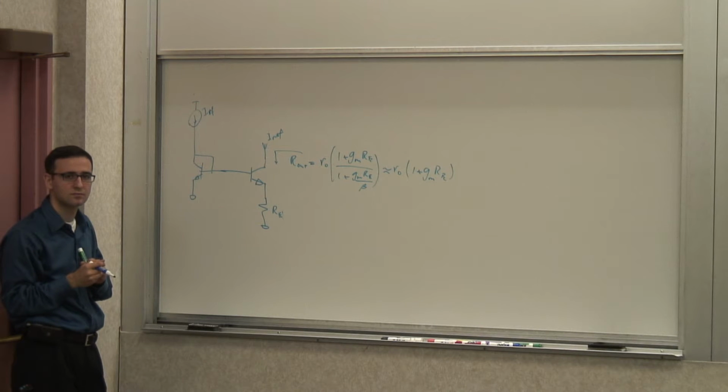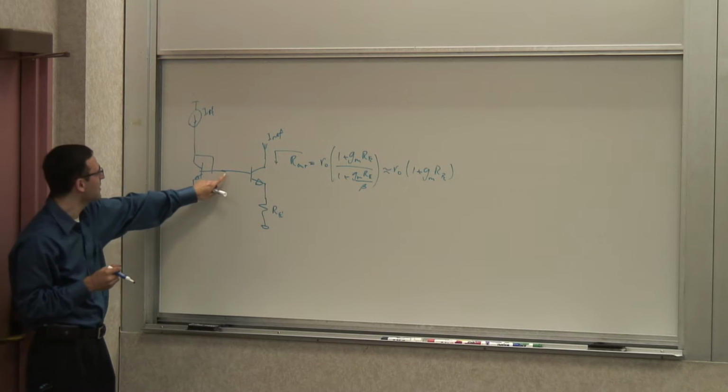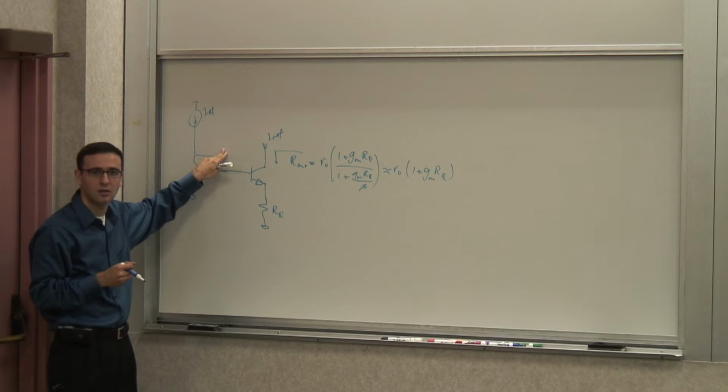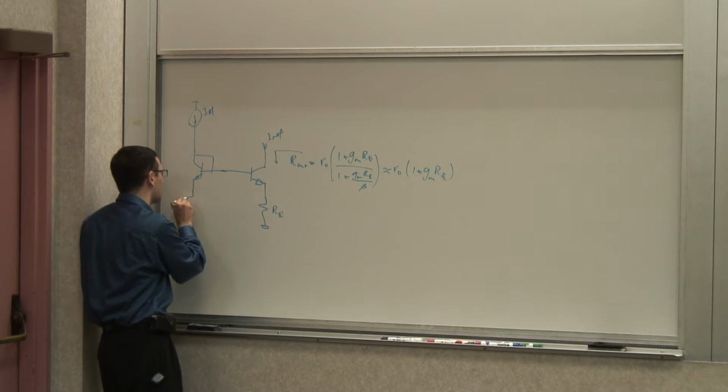Can you cascode it? Well, no, how would that help? Well, no, the problem here is that if this is IREF and if I put a resistor here, this current will become much smaller than IREF. Exactly, do the same thing on the other side.